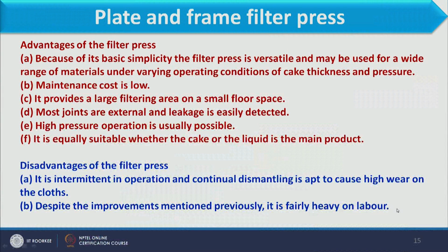Because the plate and frame filter press is operated in batch, after one cycle the complete assembly should be dismantled, and again the arrangement of cloth, plate and frame will be carried out, and therefore the life of the filter media in this case is not very long. Despite the improvements mentioned previously, it is fairly heavy on labor because continuous removal, dismantling and cleaning is required, so labor involvement is high in this press.